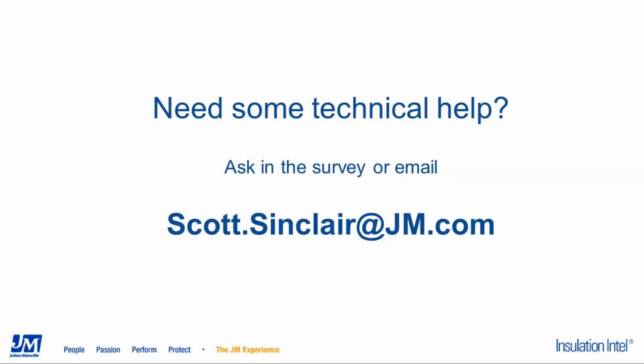Typically, your focus on low temperature, especially cryogenic systems, is looking to prevent vapor migration through the insulation system so that you don't have airborne water vapor getting to that colder cryogenic surface. If it's a cryogenic surface, it will condense and immediately freeze. Then you have issues with the risk of the ice formation doing damage to the insulation materials. So there's not as much of a focus on CUI with cold and cryogenic systems.